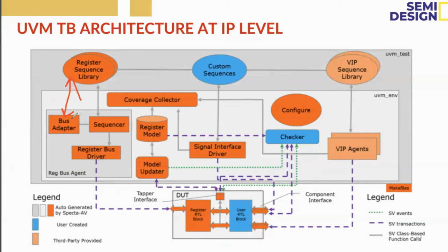So here mainly the register sequence will drive the register stimulus. The register sequence library generates the register stimulus. Mainly the abstraction layer is used for modeling the memory mapped registers and the memories in the DUT. For that it should have the register model, adapter layer, and the predictor. Here the predictor is not mentioned. Predictor will be there when we discuss the concept in depth. There I will tell you clearly.